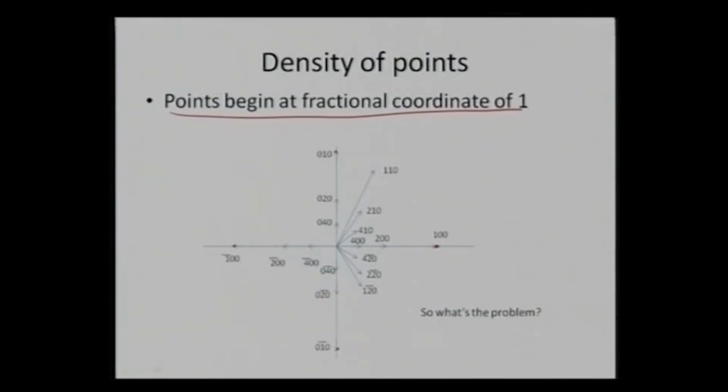But as soon as I start coming into the crystal, I will see that I have different planes, plane 200, plane 400, they all start falling from the outside to inside. Similarly, I will have all those points available here as well. I have 1 1 0. So I will have my 1 bar 1 0 somewhere here along the same side.